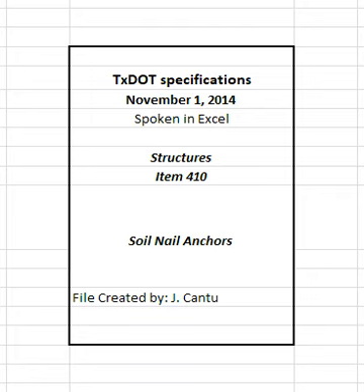Perform initial tensioning to take the slack out of the testing apparatus at 5% of the required test load unless otherwise directed.